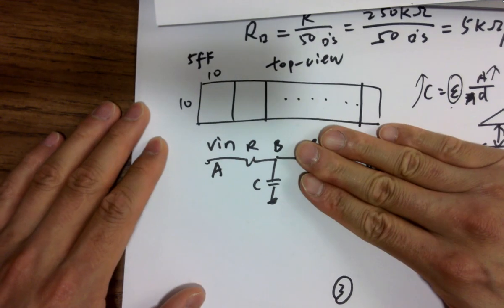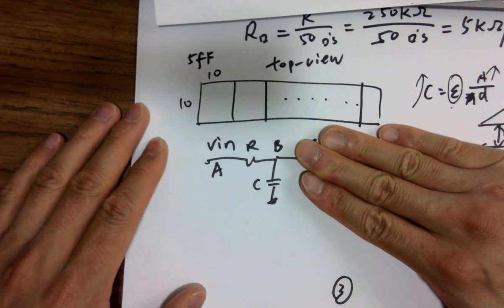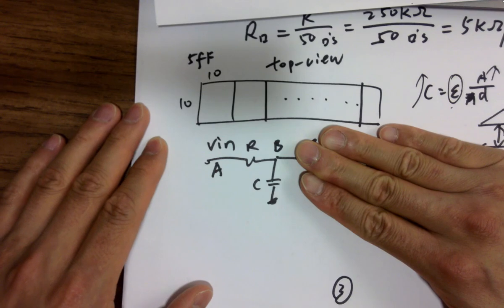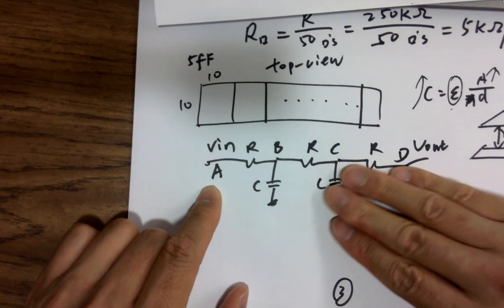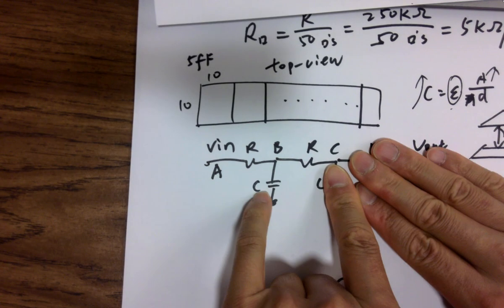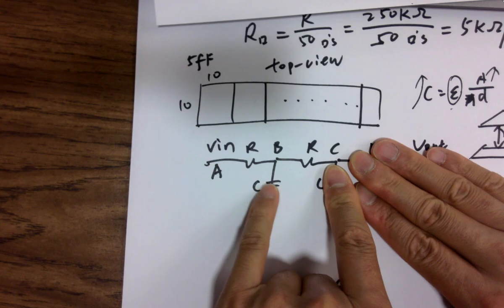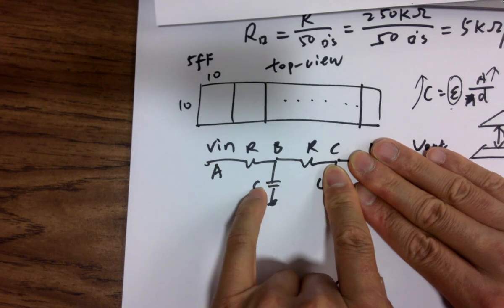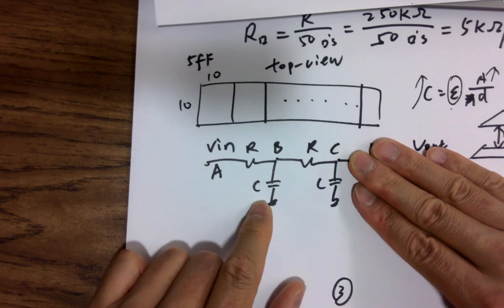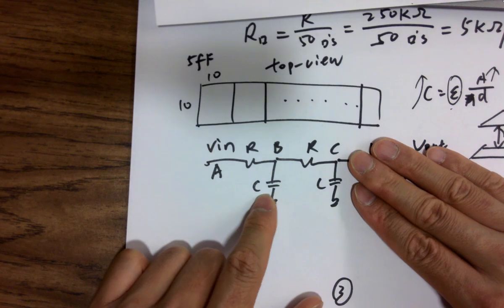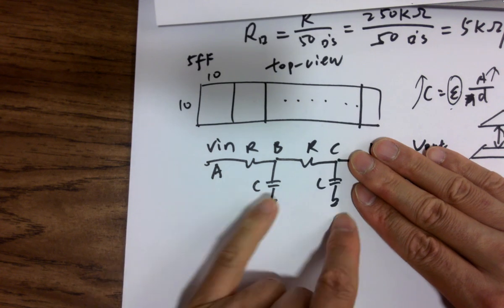A to B is simply 0.7 RC. So what about A to C? It's getting a capacitor in the middle, which makes things complicated. But the way we do that is we just add all the contributions of the time delay of the caps together.